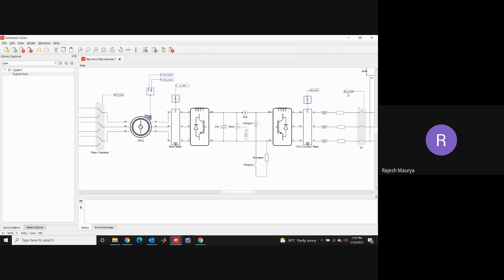And here I have taken the feedback output for this contactor as GSC underscore state. For both these go to blocks, I have taken the scope mode as local. So from right now onwards, I'll take every go to block's scope as local instead of global.